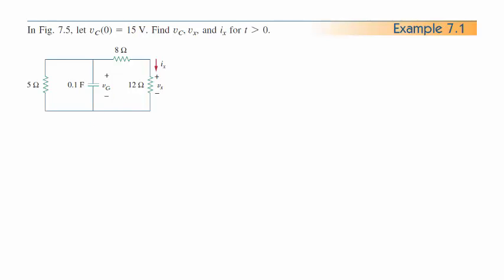So this problem probably exemplifies that for us. We always have to get it into the standard form of one resistor and one capacitor. I could have capacitors in series and parallel that I have to reduce to one equivalent capacitor, and I can have resistors in series and parallel, and I have to get the equivalent resistance, which is what this circuit is all about as an example. So you get the equivalent capacitance and the equivalent resistance, and then you can get the RC time constant, and then you can mathematically describe the natural response of that circuit.